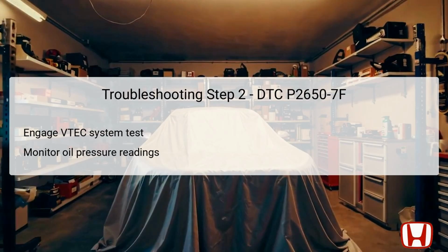If the readings meet the standard, yet the DTC remains, there may be a defect in the gauge or sensor output that needs addressing. However, if the oil pressure is below the specified level, it indicates an issue with the oil flow or its management within the system.